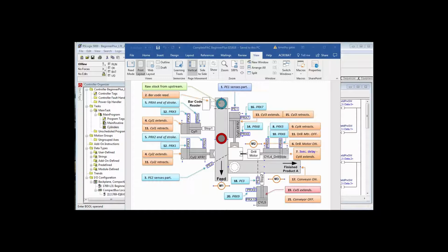So we have 3 number 11s. And there's no reason when we turn the drill motor off not to include that with telling those 2 cylinders to retract. And then, of course, after 11 comes 12, which is proxies 1 and 3 saying, okay, those cylinders are retracted. Now, we have a finished part in the workstation there in front of the drill motor. And we've retracted cylinder 1, but really specifically cylinder 2. So the part is no longer held there.